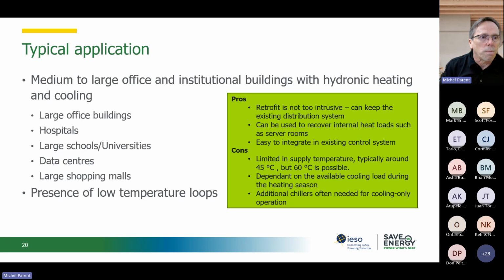Now, the one thing you have to be very careful about when you start using heat recovery chillers is that you have to stop doing free cooling. When I said that you want to use your heat recovery chiller to provide heat to your building and stop throwing heat outside, always remember that a cooling tower or an air side economizer rejects heat outside your building. When you use free cooling, you are basically throwing heat outside the building that could be used to heat the building.